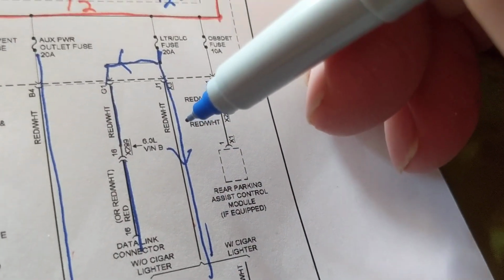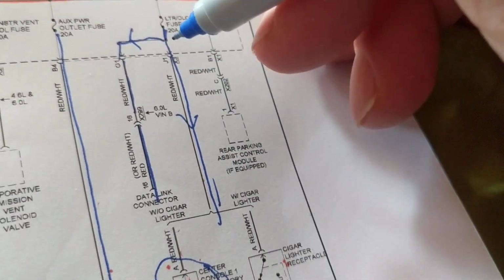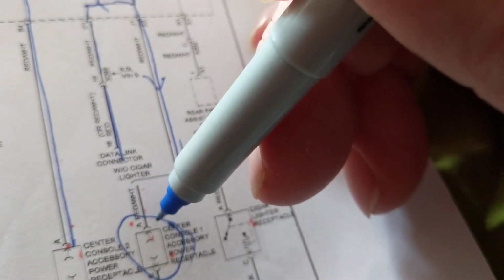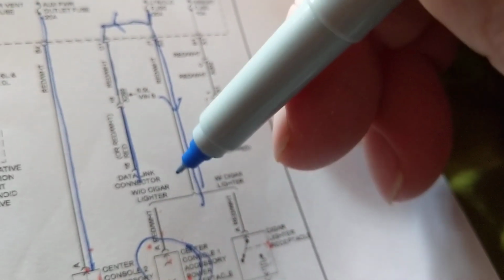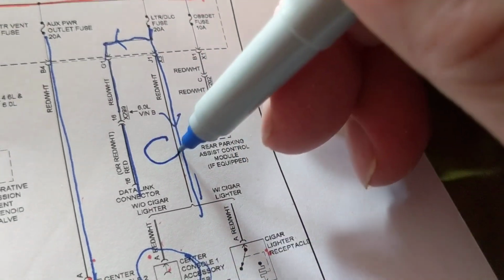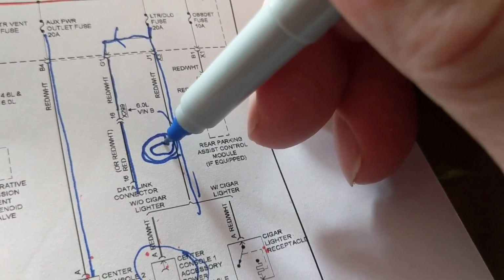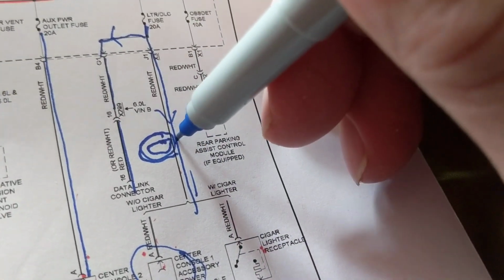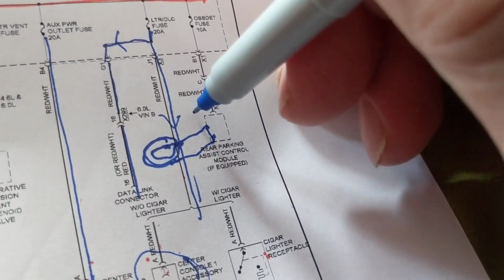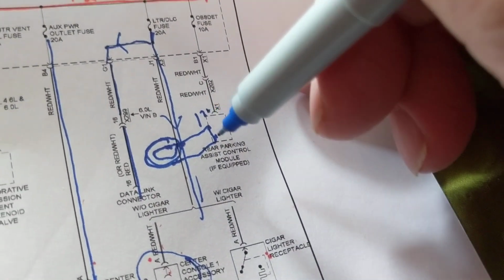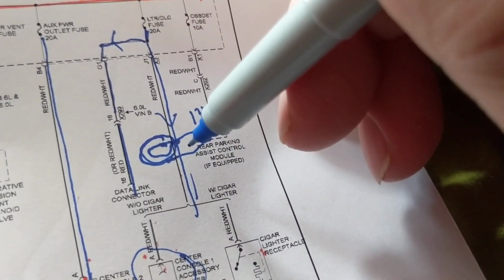This line is open. Could be this power receptacle is bad. There is a connector that goes to the back of it. Like the cigarette lighter, you have to take the panel out. Sometimes for GM, there's a retainer, a black retainer. Then the actual receptacle goes inside of it. Well, the back of that one has a connector, 2 wires, 12 volts. Could be the connector maybe broke, or it could be the receptacle itself is not good.